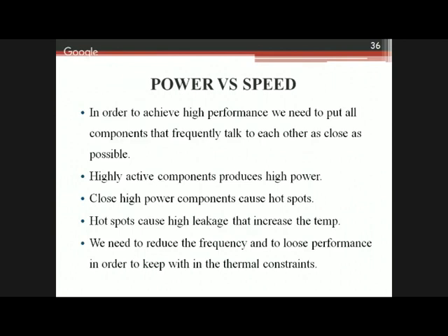So in order to avoid the hotspot problem, we have to place the components separate from each other, and we have to reduce the frequency. But reducing the frequency means we have to reduce the speed. So from the design point of view, there is a trade-off between power and speed. We have to manage both of these constraints.